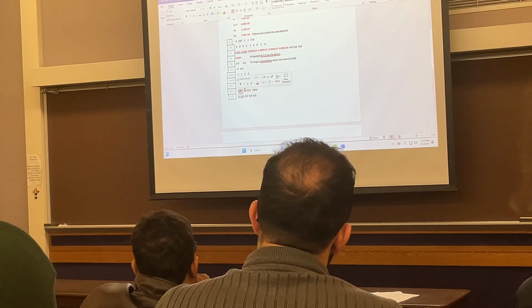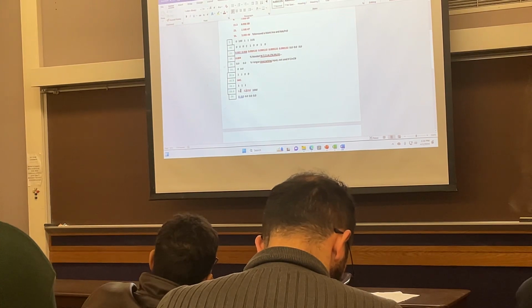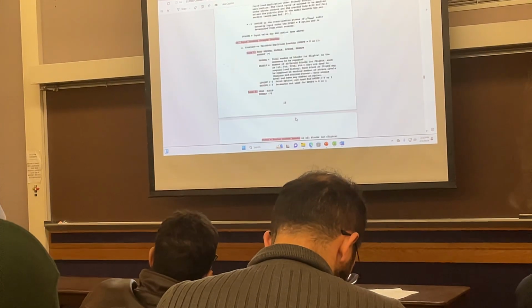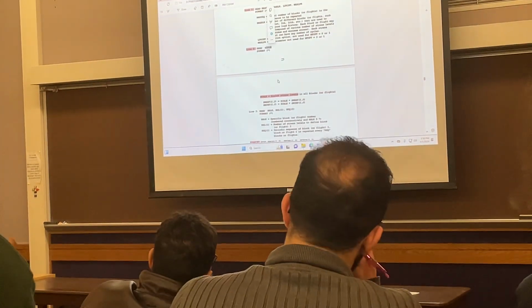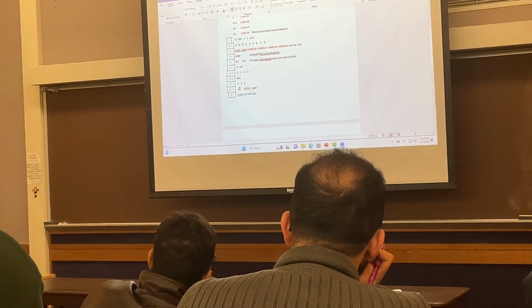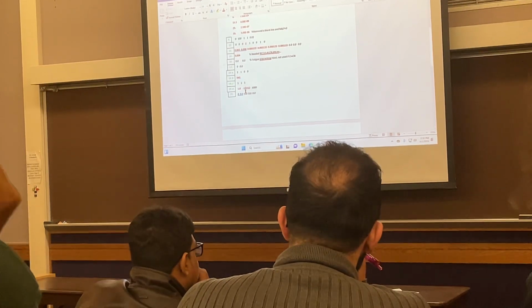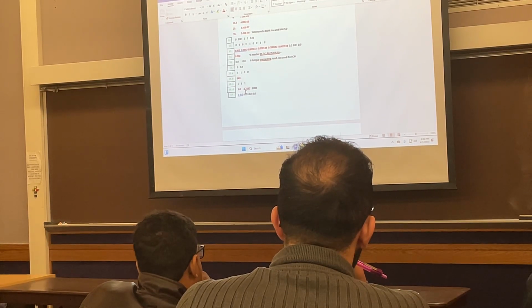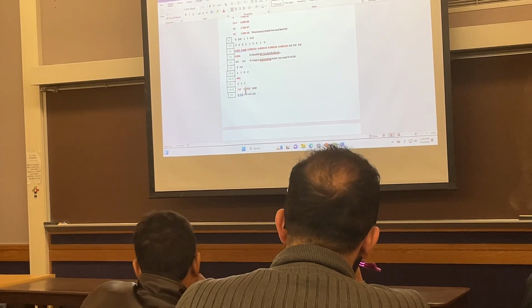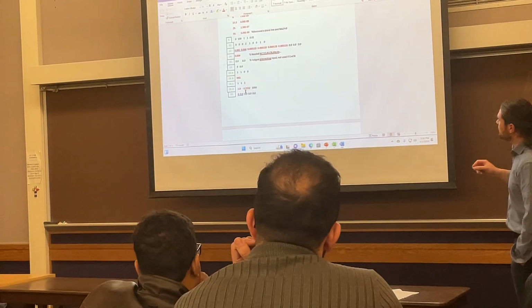These two are for maximum stress and minimum stress. It's number 18. So it's referred to as a scale. So it works like this. What you need as an input is the minimum stress or maximum stress. For any fatigue calculation, we need the minimum stress and maximum. So the way that you put it in the software is basically, assume that your maximum stress is 642.